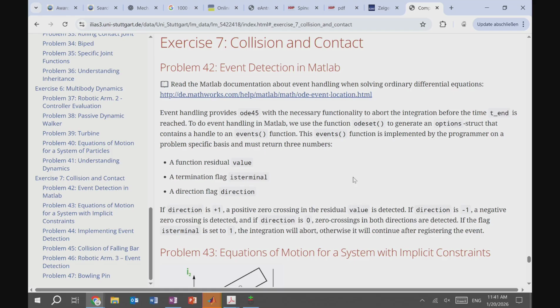So you get to compute a collision, and then you basically get a loop, constraint dynamics, because you go ground, link, right? The 3 links of your robot to the end effector, wire, ground. So you have a loop, and you get an interesting constraint. What's the constraint? The length of the wire is constraining the end effector. Where can the end effector move?